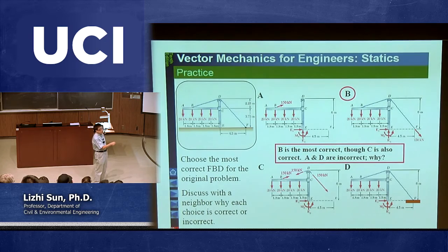The reason I'm saying that, if you go back to look at your second midterm, right? There's one question, something related with this. Okay? So if you want to cut here, you need to give 2 forces. The reason you give 2 forces is because both point B and point D are part of the rigid body. And if that's the case, you really do not need to cut. But if you really want to cut, then no problem. You gave the forces correctly.